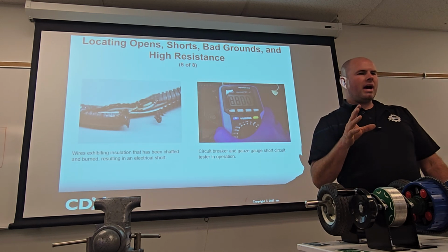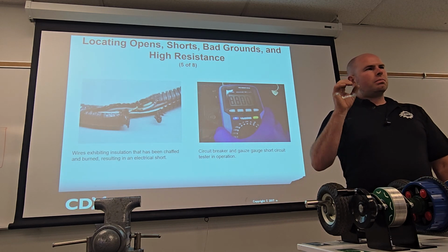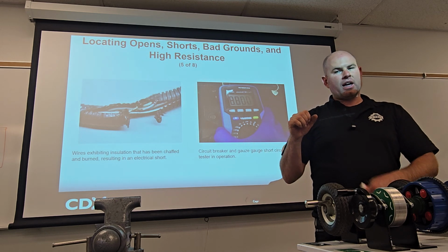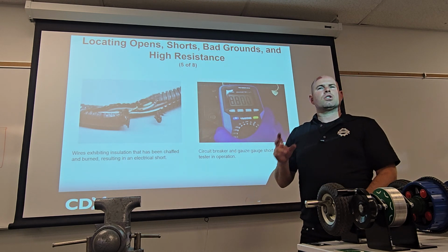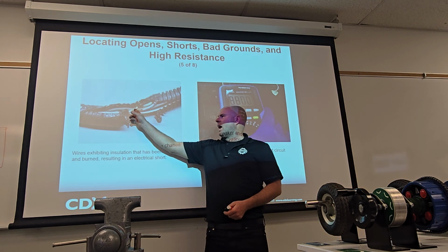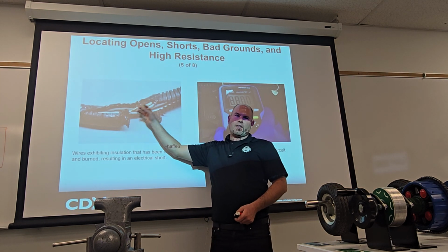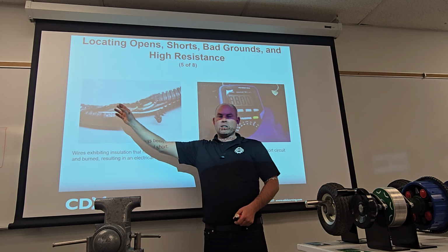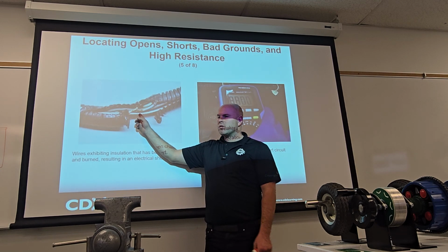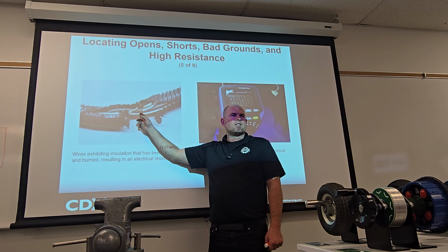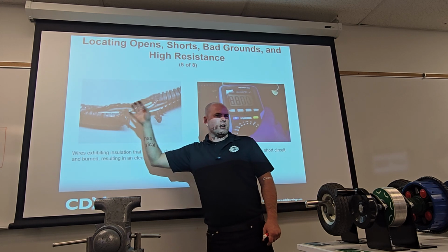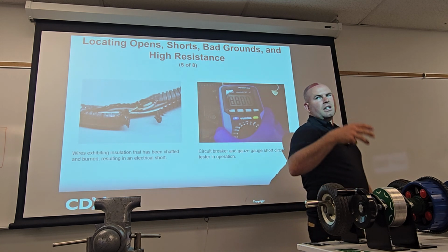But a short to power is kind of weird because 12 volts is usually inside of another wire, or on the positive battery terminal. So a short to power would be pretty rare because this would have to happen to be shorted to another wire that would have to be stripped. Make sense? So if this wire is positive and this touches the outside of the insulation, there's no connection there. It's not shorted. You'd have to actually have multiple wires that are missing insulation to cause that.